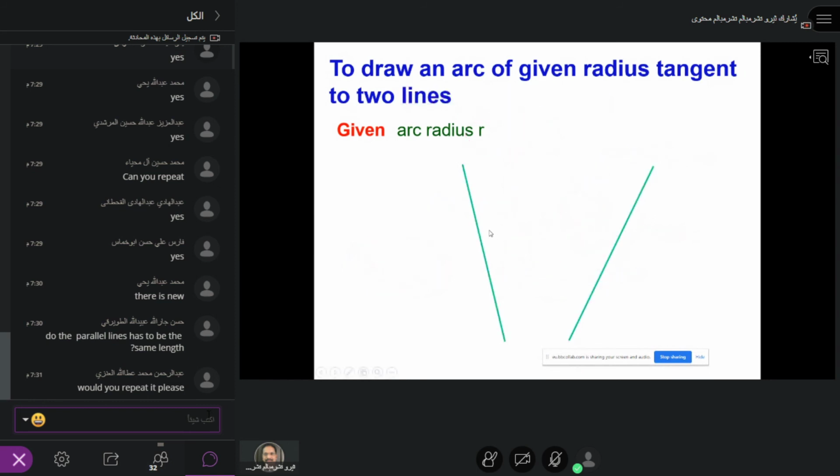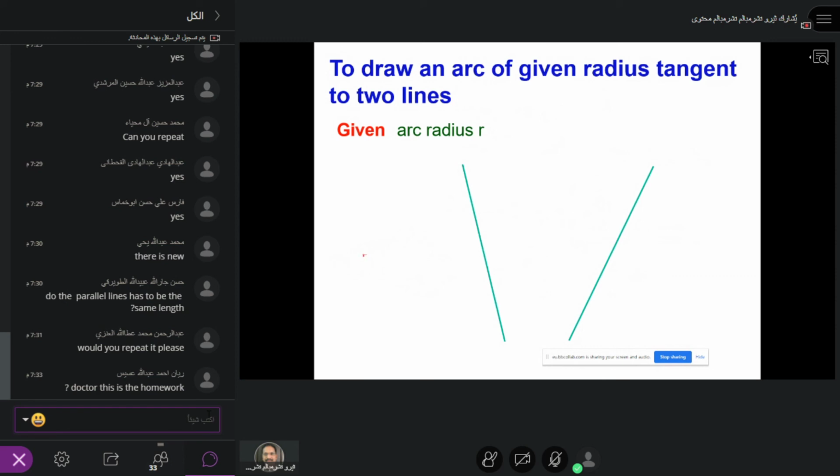So first you draw, let's say, vertical or horizontal, doesn't matter. Let's take a point, and then using your protractor, draw two lines. Make sure that this will be 45 because that is given, right? This line can be of any length, no problem. Then take some point here, and the radius is given as 15 millimeters. So take the radius and then use your protractor and draw this parallel line, the tangent line basically, as here.